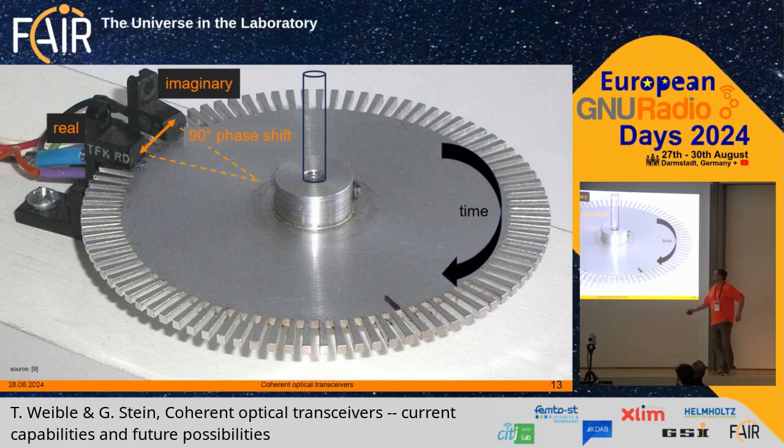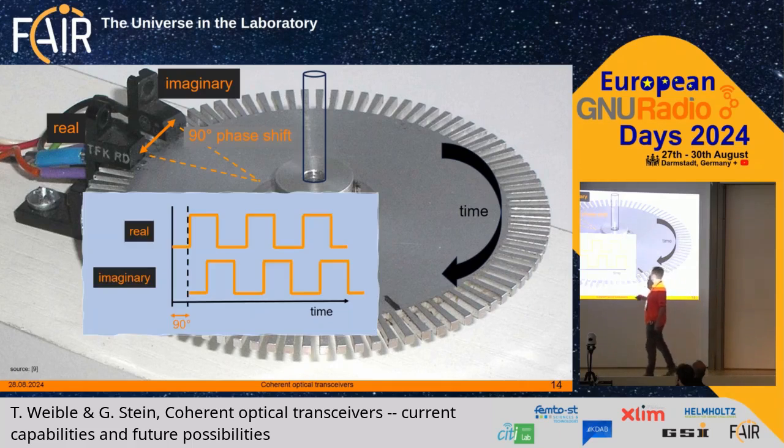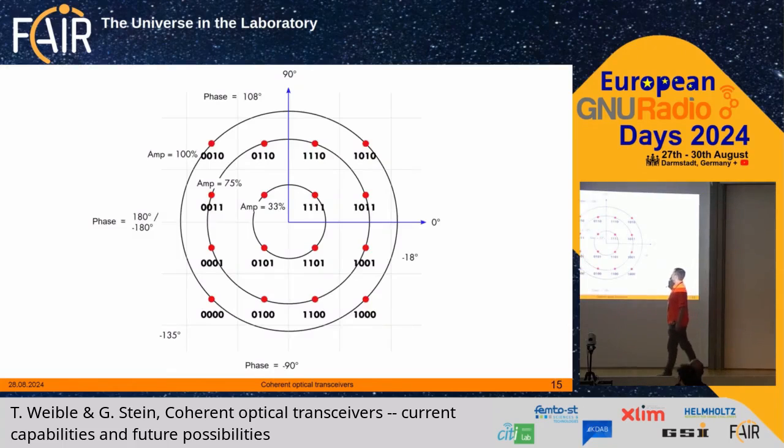The thing is, if you have phase shifting and you look at the signal and imagine you're moving it, you can determine the direction. If you want to measure, for example, rotational speed, into what direction this disk is rotating, you cannot find out with just one reader. But if you get a second one and you check the pattern, which part is on one in the real and the imaginary part, and what kind of phase shifting we have, you can find this out. You can see in which direction this disk is spinning. So yeah, that's another example.